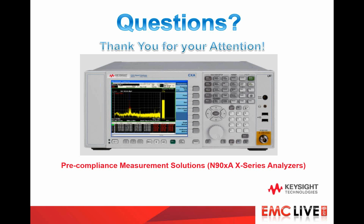Great. We have a lot of questions coming in. Let me take a look. Is the use of preamplifiers required when doing EMI measurements? It's not required, but preamplifiers are available, so that'll increase your sensitivity by amplifying the signals from the noise floor. So your signal to noise ratio will increase using preamplifiers, so you can pick out some of the weak signals a little bit easier from the noise. And on the display here, you can kind of barely see a line where the threshold is, so that's for Part 15 sweep, so you can see where the noise floor is versus where you have some failures indicated in the red.